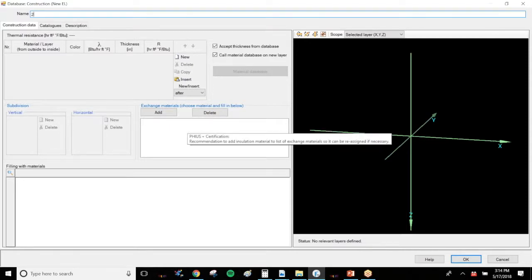Okay, so I'm going to call this 2x10 framed roof, 5 inches polyiso above. Or sometimes I'll start it with roof and call it 2x10 with fiberglass, 5 inches polyiso. Something like that. Something where you can read that and understand what the roof actually is that you've built, rather than going into the assembly and determining that.